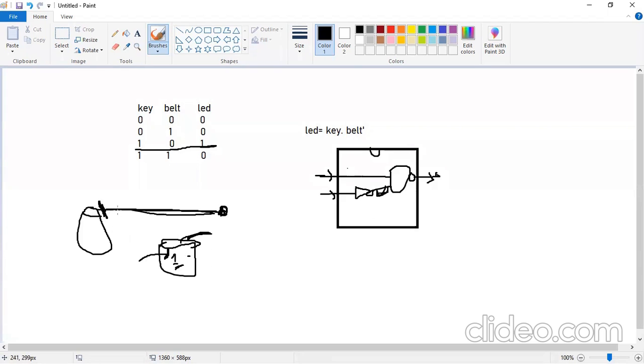But in the case of a wire, you have to change the storage thing, and only then will you be able to change the value on the wire. Otherwise you can't drive it. Suppose you are driving a value 1 directly on a wire; you can't change it to another value. So first you have to use a storage data type to change the value of the wire again and again.